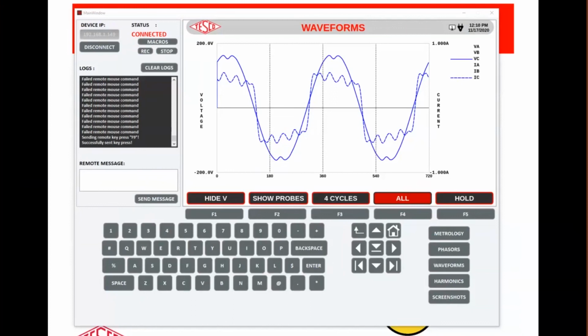But nominally, they don't have to be efficient at higher frequencies, and so they're designed using core materials that don't work all that well at higher frequencies. That has the advantage of blocking those harmonics from getting back on the network, but it has the disadvantage that it turns them into heat in that transformer.